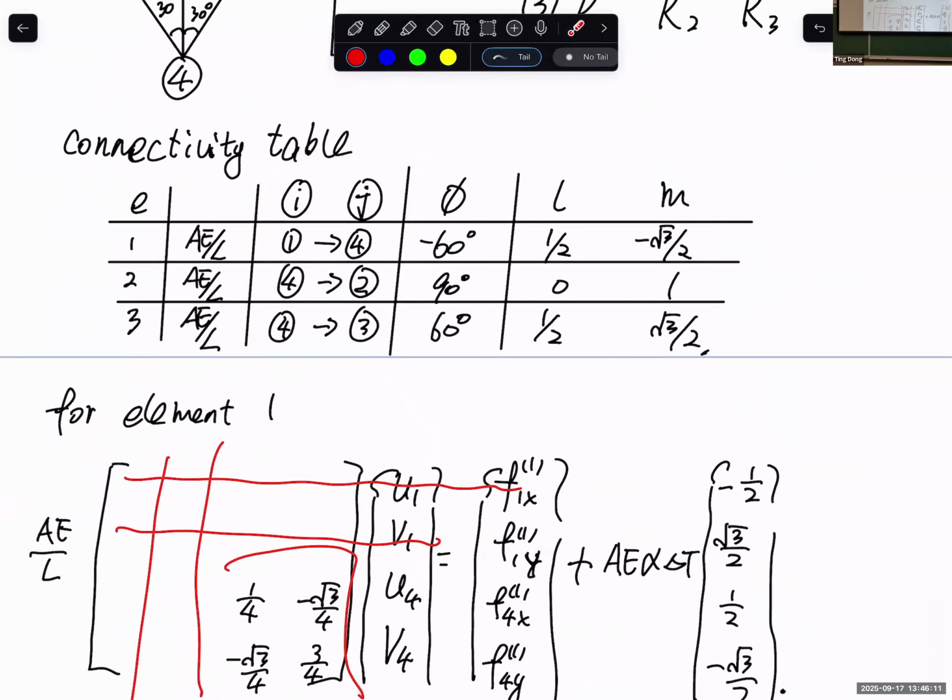For the displacement field, I wasn't sure if I did it correctly. Do you have displacement at this point, this distance from the wall? Yes. For the 1D bar, stress and strain are constant for each section. Since strain is the first derivative of displacement, the displacement within each section changes linearly. In FEA, everything is calculated at the nodal displacements. You calculate this one, and these two are 0, and in between it's a linear change, so you just use a straight line. It's not an assumption, it should be linear.